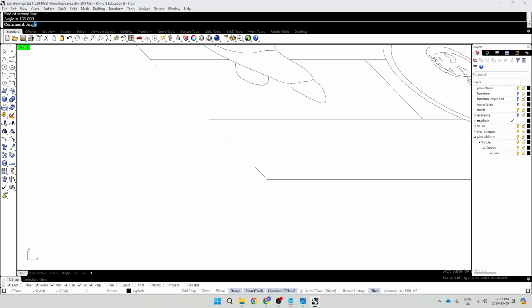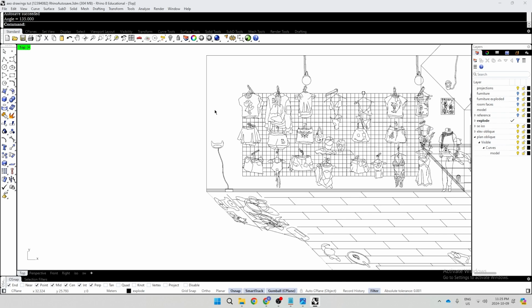And there's a really handy nested function of this command. You click on two objects, and then you can choose the two lines to measure. I'll choose it like this. Yeah, choose these two lines, and then use the angle command again, and it will just measure it automatically for you. Great.